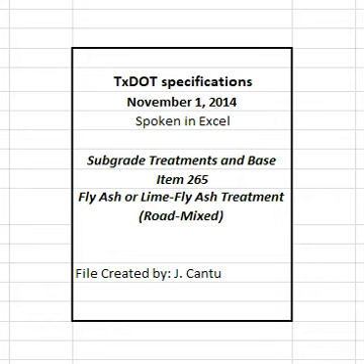Finish grade of constructed subgrade to within 0.1 feet in the cross section and 0.1 feet in 16 feet measured longitudinally. Correct grade deviations of constructed base greater than 1/4 inch in 16 feet measured longitudinally or greater than 1/4 inch over the entire width of the cross section in areas where surfacing is to be placed. Remove excess material, reshape, and roll with a pneumatic tire roller. Correct as directed if material is more than 1/4 inch low.